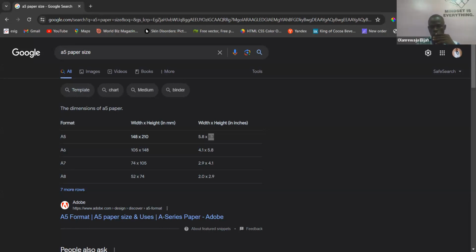Right. So now I told you guys, because probably we want to print it, let's say we want to increase the resolution to maybe 150. Then the color mode, let's also use CMYK, because probably at the end of the day, we want to print it and share it with our clients, our potential customers, right? So you can choose CMYK color mode.